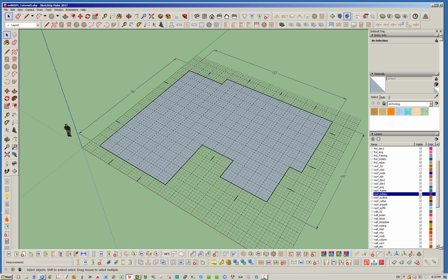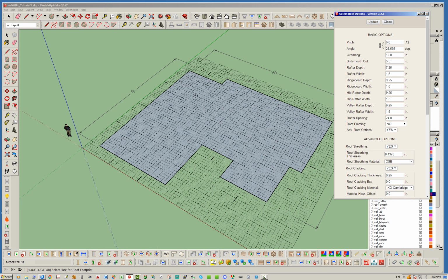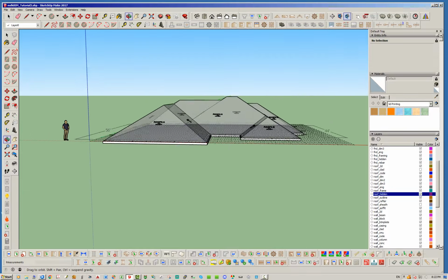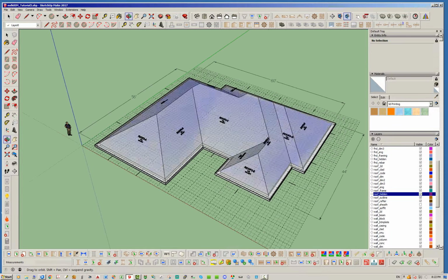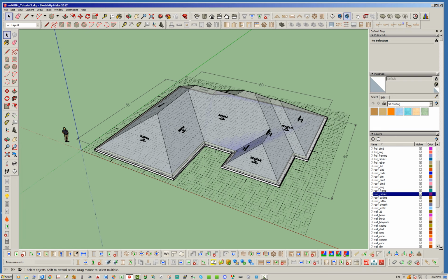So now let's go ahead and drop a complex roof in here. Regular rafter roof, and I'm going to leave the roof framing off. I'm going to say with an 8/12 pitch roof, and hit update. And then just start here, doesn't really matter where. And there's our roof. Okay, and maybe that roof overpowers those walls. I don't know, but we'll find out.